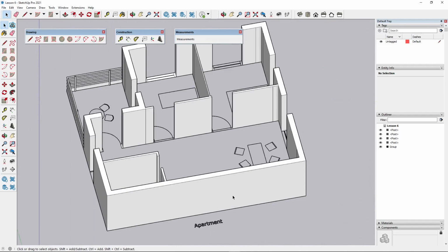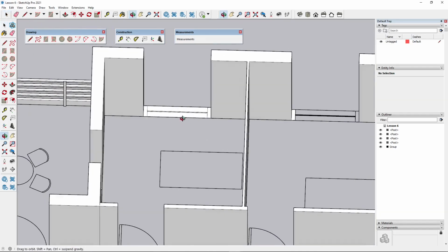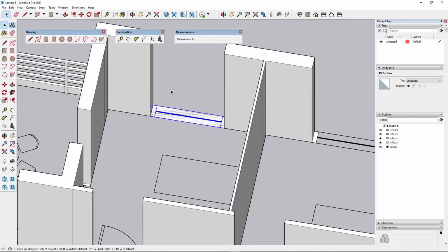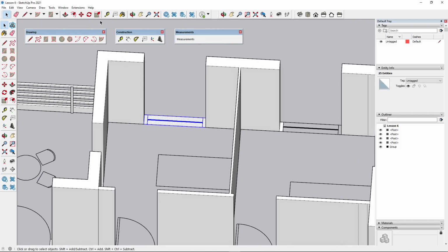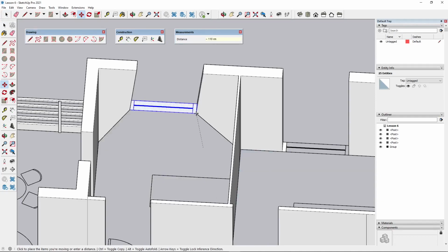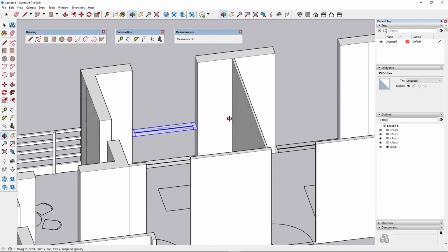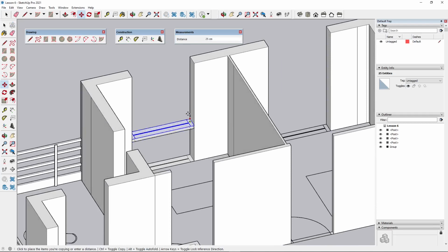Okay, now let's move to the window. So in the window here, I have one already prepared, so I will select that and then create a copy again. So move up and Control, and let's say 80 centimeters. Okay, and well, also I will copy this once more and say this is gonna be the height of the window. So I don't know, maybe another, well, let's say 100.